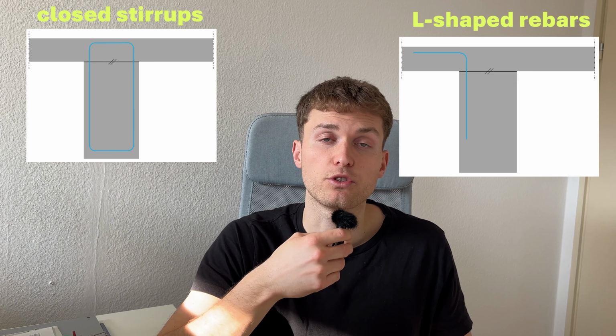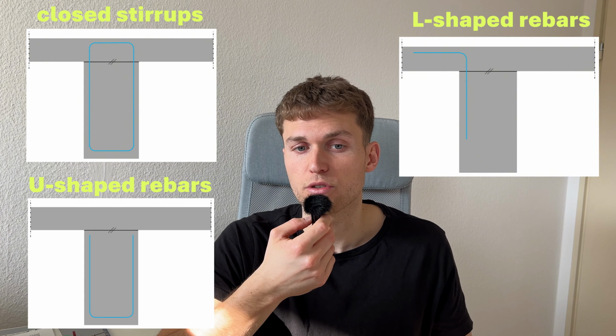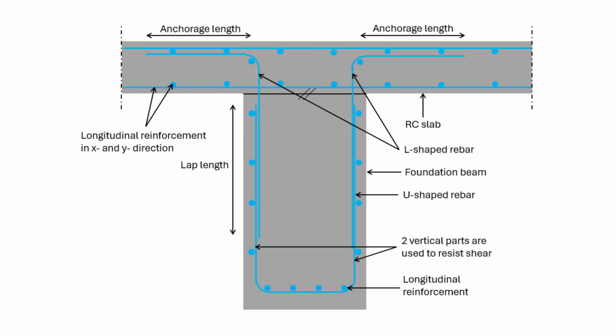Now let's look at some examples of shear reinforcement connecting two elements. Shear reinforcement are usually vertical rebars. To account for the correct anchorage length, usually closed stirrups, L-shaped or U-shaped rebars are used. Now, when you connect two elements with each other, like for example a foundation beam and a slab, from my experience, construction companies usually rather use L or U-shaped rebars instead of closed stirrups.